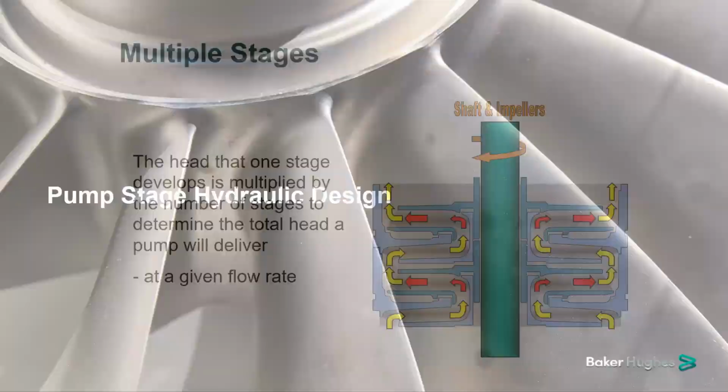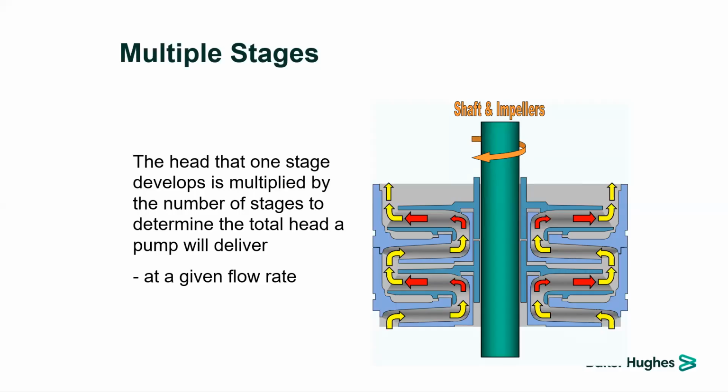With that, we have already explained how the fluid goes through the impeller and diffuser and how the energy is transferred and stored as kinetic energy and then transferred to potential energy, creating the required head and delivering the required value to lift the flow to the surface. That is the theory of operation of the ESP, illustrated in photos and in the flow path of the fluid.